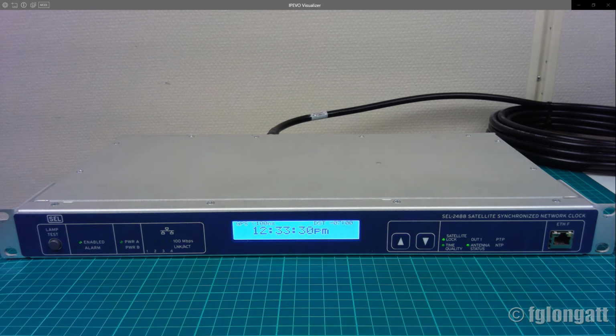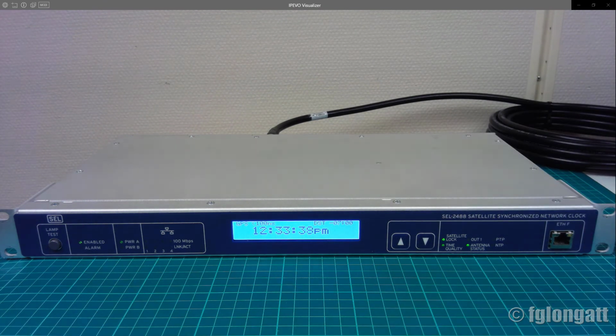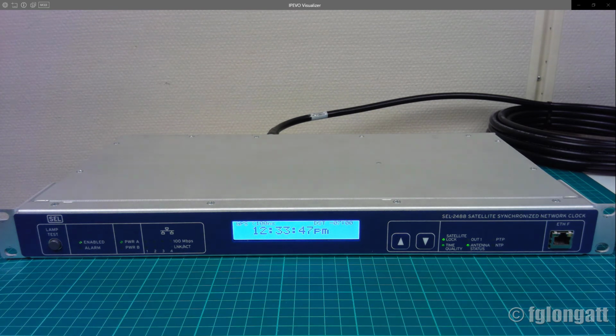This relay is coming from the US, United States of America, and as a consequence, you can see here that it is using the time zone of -7, okay? And over here you can see some information about the precision related with this device in terms of time, okay? As you can see, now the device is ready and up and is providing time with very good quality, and we are ready to use this timestamp for our protection system and for control system, okay?